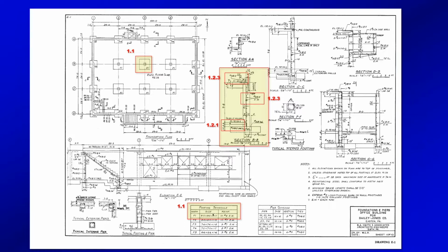Nah, you wouldn't do that. You'd make it 2 feet. I know a contractor would. And then it asks for what the reinforcement is, which would be 10 number 8s each way. Okay?